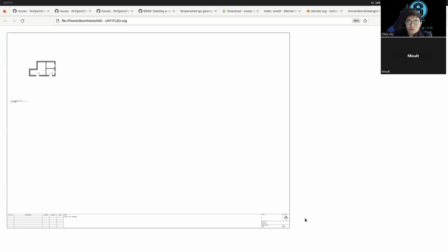to end, not just your drawings, not just simple walls like this, but everything, your cost plans, your Gantt charts, your carbon takeoffs, your energy models, your light simulations, your structural analysis, your MEP systems and system connectivity calculations. You can do all of that end to end in pure native IFC, no import, no export, 100% free software that everybody can see how it's built and tailor it to their own workflows.